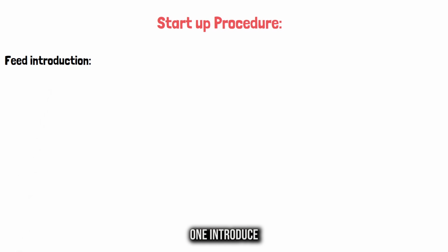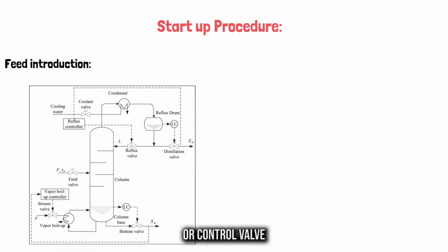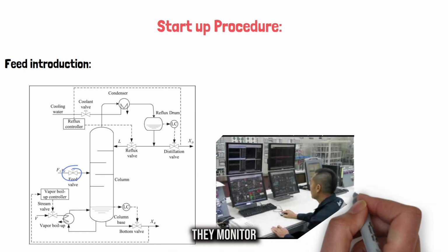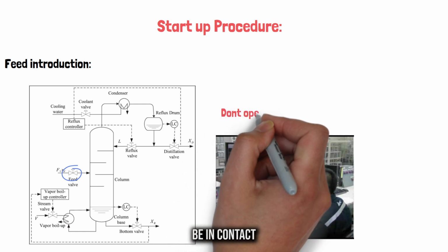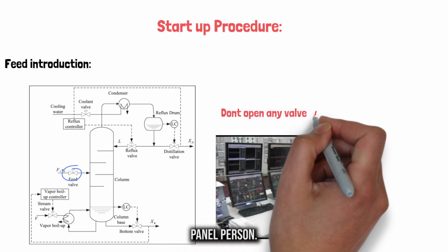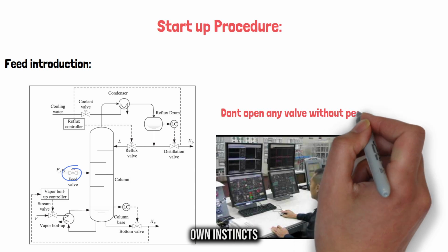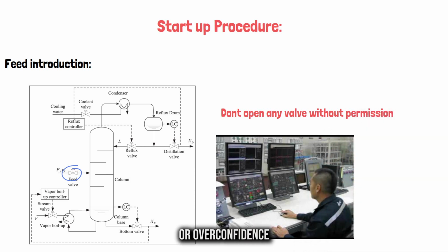Then next, startup procedure. 1. Introduce the feed by opening the valve or control valve with the help of a panel person, because they monitor flow and pressure. They assist you from start to end, so every time, be in contact with a panel person. Don't open valves by your own instincts or overconfidence.